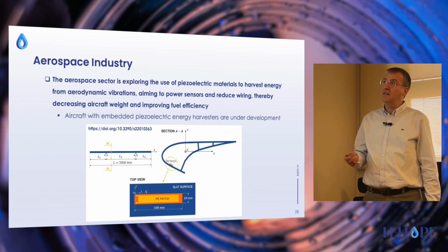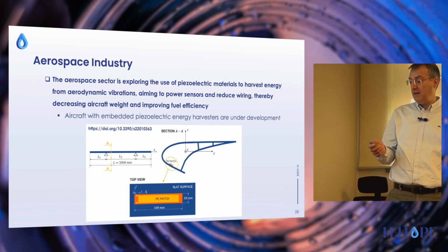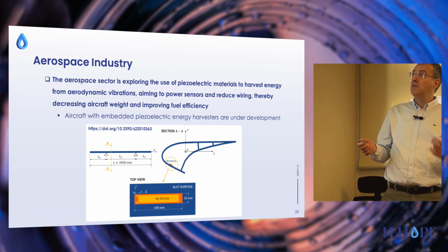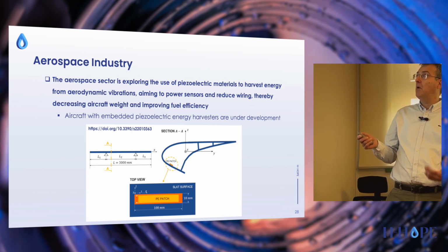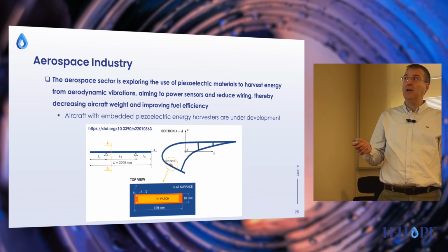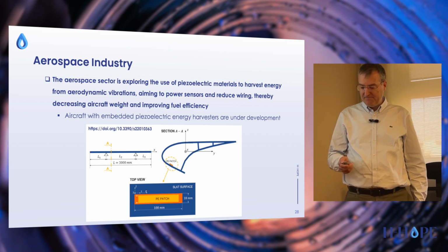And since a long time ago, one of the most important applications of these piezoelectric patches is obviously the aerospace industry, which is exploring the use of piezoelectric materials to harvest energy from the vibrations, aiming to power sensors and reduce the wiring, thereby decreasing aircraft weight and improving fuel efficiency. For instance, you can see here that inside the slats, they are trying to install this type of piezoelectric systems in order to harvest the energy.